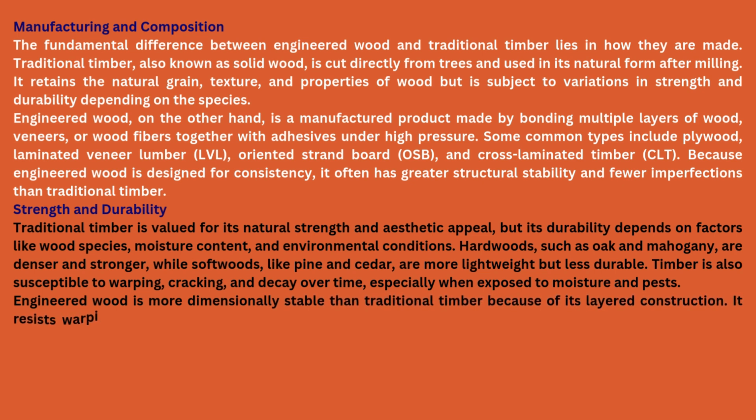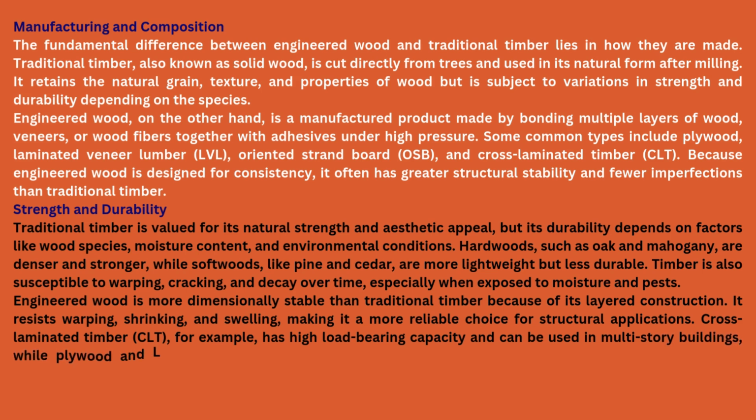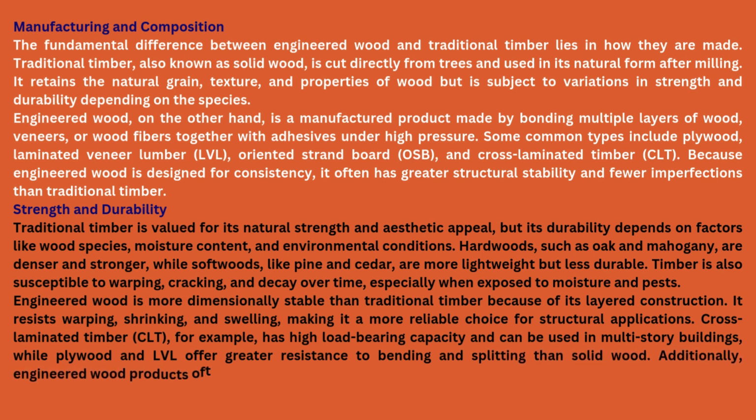Engineered wood is more dimensionally stable than traditional timber because of its layered construction. It resists warping, shrinking, and swelling, making it a more reliable choice for structural applications. Cross-laminated timber, CLT, for example, has high load-bearing capacity and can be used in multi-story buildings, while plywood and LVL offer greater resistance to bending and splitting than solid wood. Additionally, engineered wood products often come pre-treated to resist moisture, insects, and fire, increasing their lifespan.